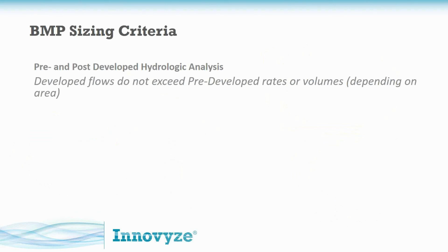We found that detention ponds don't really do a good job of truly mitigating the impacts downstream. There's lots of stream erosion, lots of water quality concerns. So now we need to retain and infiltrate a volume, to keep our discharge volume less than or equal to our existing conditions. So that's where we really begin to need some of these green infrastructure practices to do that.